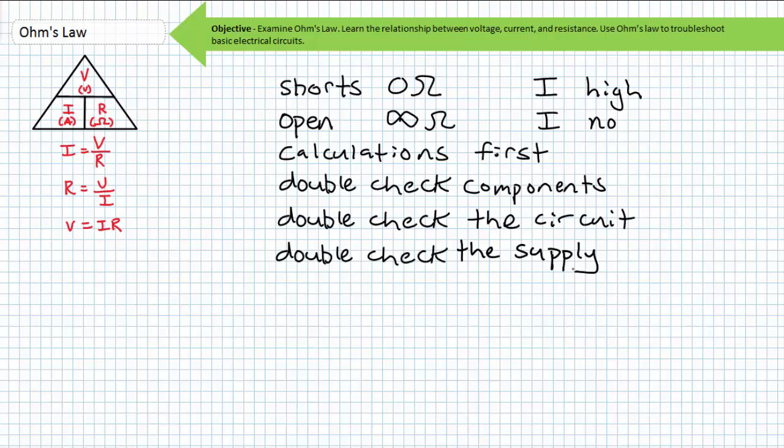Supply the circuit with the correct voltage. Use a voltmeter to make sure the power supply is set properly before you begin. Measure it again when it's hooked to your circuit. When we get to series circuits, I'll explain why this is necessary. I know there's an analog needle on the front of some power supplies, but they're inaccurate almost to the point of being useless. Use your DMM.